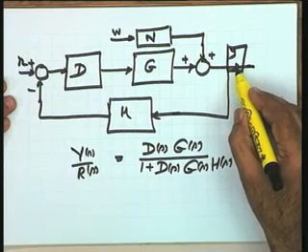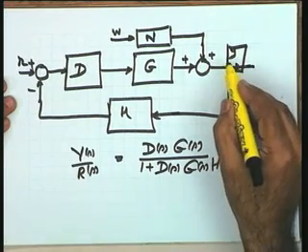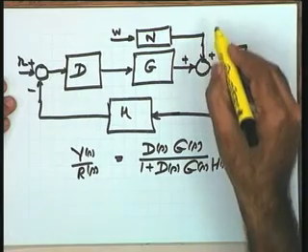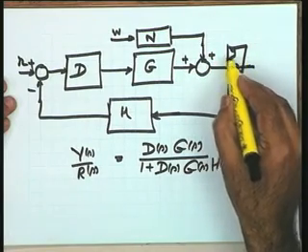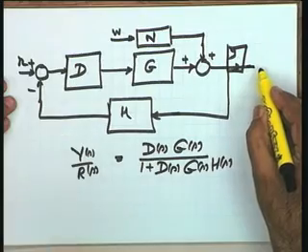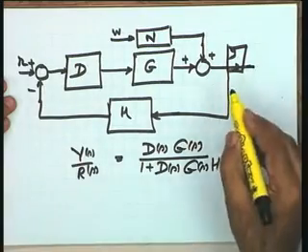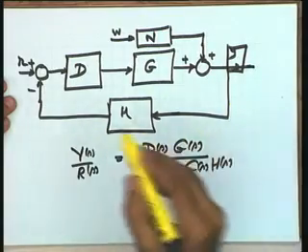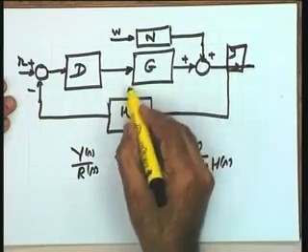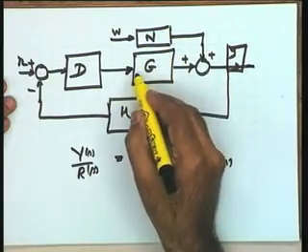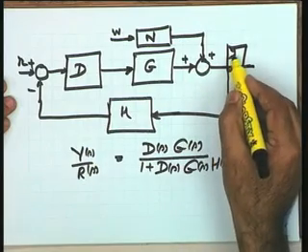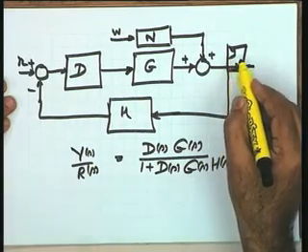So any changes within this component or any environmental effect on it is going to directly affect the system output. Therefore, we try to compensate for the loss by putting in sufficient margin, or by increasing the open loop gain of the plant, so that after the loss of gain, the output level is acceptable to us.